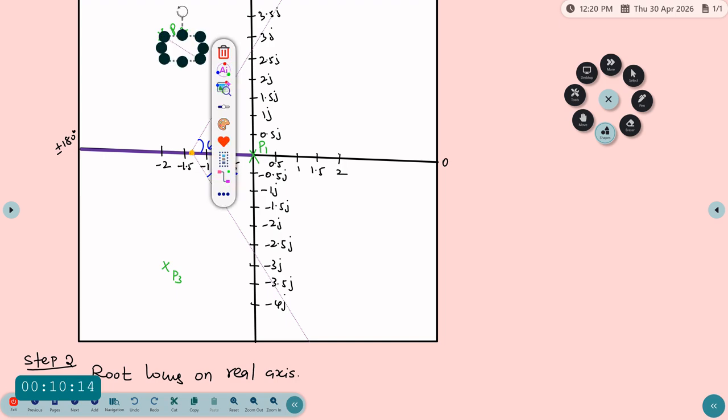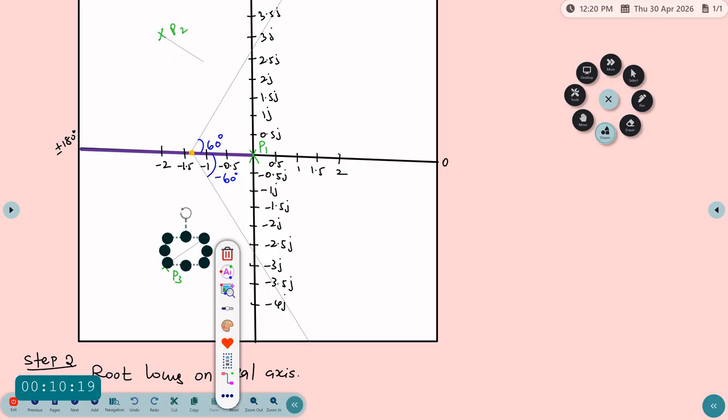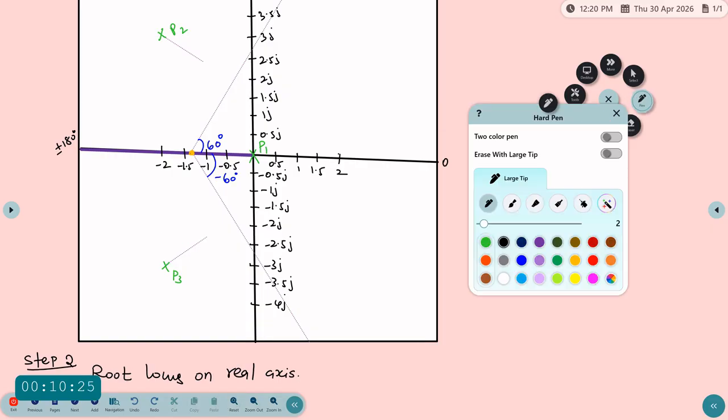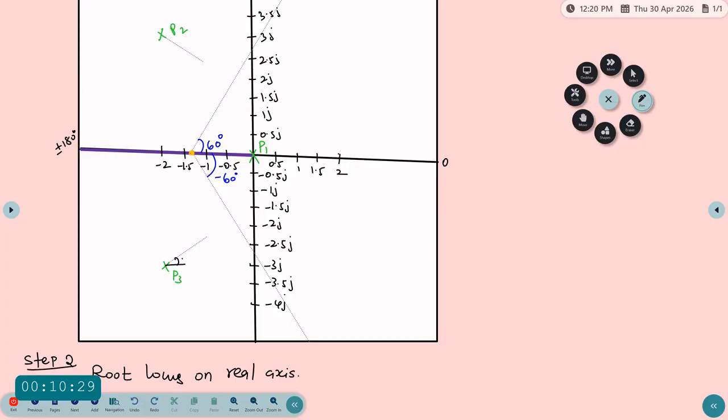Similarly, angle of departure at P3 is plus 33.3. Just to draw a dashed line from here, that is more than sufficient. So we can write, this phase angle is 33.3 degree. This is minus 33.3 degree. Now step number 5 is over. We marked those phase angles here.